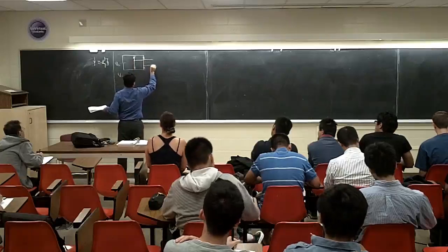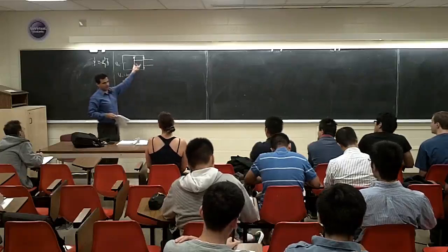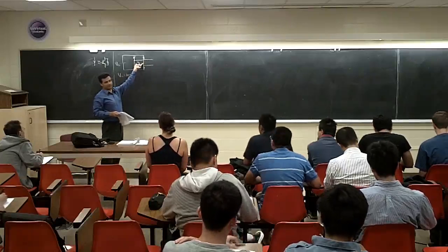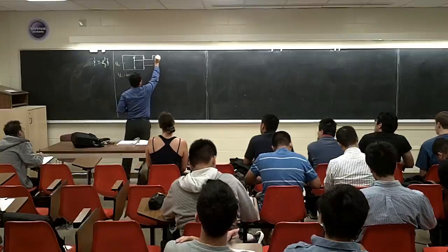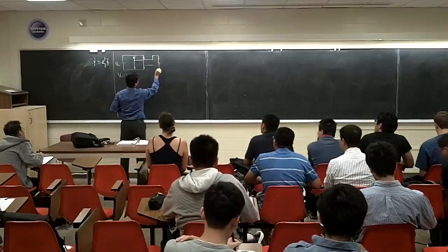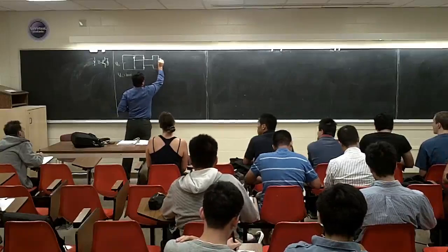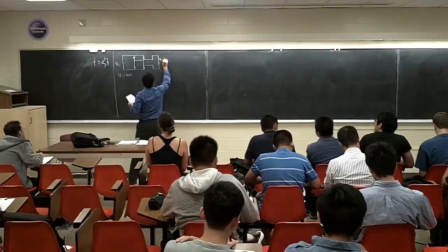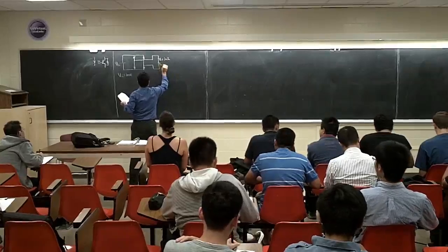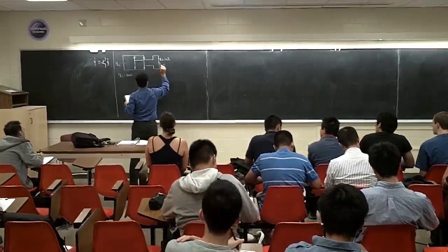This is the output of this inverter, right? We put a load here. Last time as well, you put the load right in the middle. You can bring it here. This is the load we have. There is an RL load. R is 10 ohm, and L is 25 millihenry.